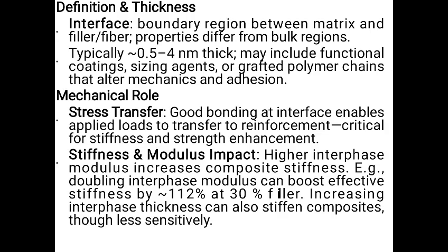and it's critical for stiffness and strength enhancements. Stiffness and modulus impact. Higher interface modulus increases composite stiffness, that is, doubling the interface modulus can boost the stiffness by about 112 percent with a filler of about 30 percent, and increasing the interface thickness can also stiffen the composites even though it has less sensitivity.